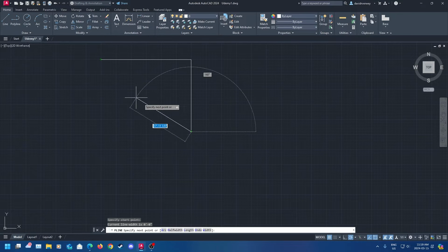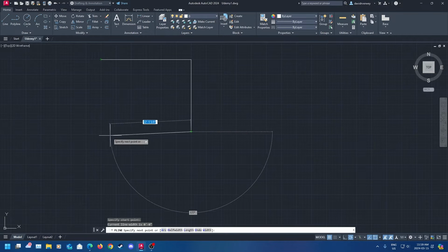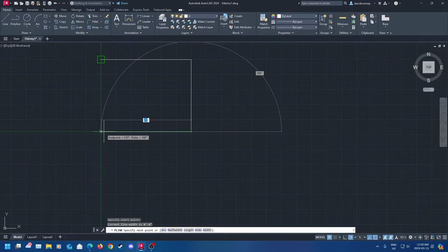You can see when I'm drawing, there are multiple ways to do this. I could just go straight and do what I did the previous two times and type in my commands. But once you have half of a rectangle, you're going to notice AutoCAD does some math for you, and it tells you that you've been using this line, which is connected to another line, which is connected to what you're drawing, and it looks like you're trying to create a square of some kind.